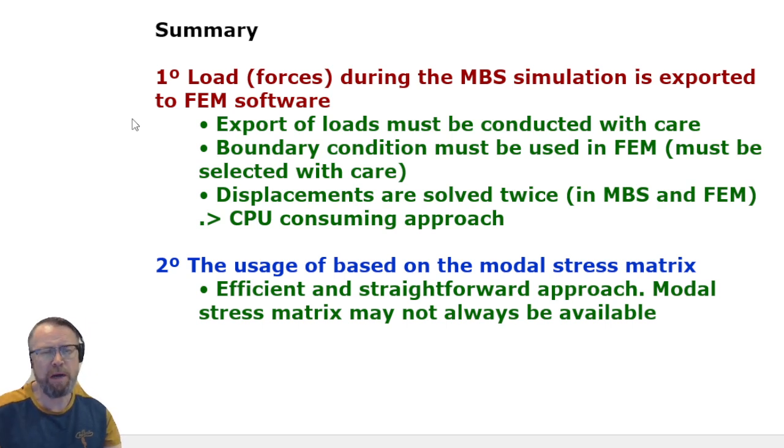This is how you can build stress histories. Or you can use a modal stress matrix, where you make use of the information about the kinematic matrix, modal matrix, and matrix of elastic coefficients. And once you do that, you can plot the stresses directly in multi-body software.